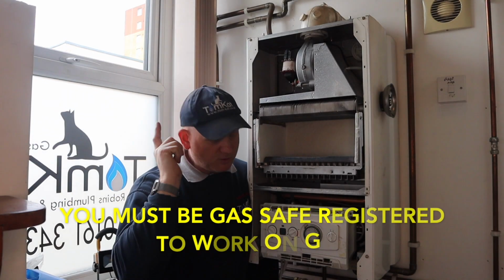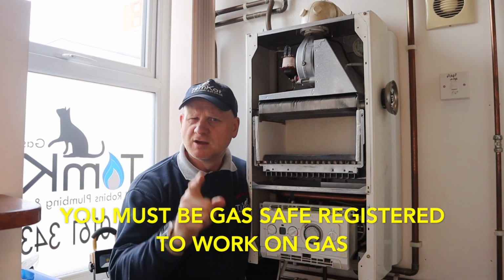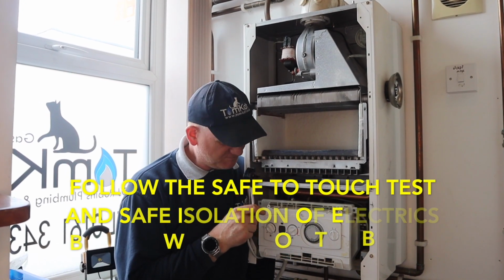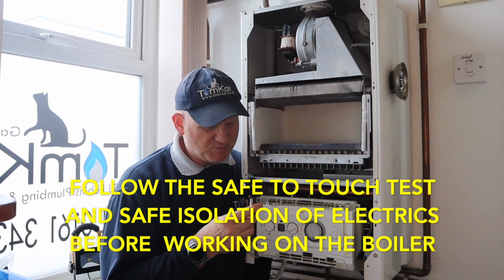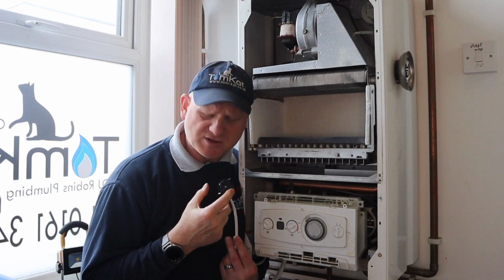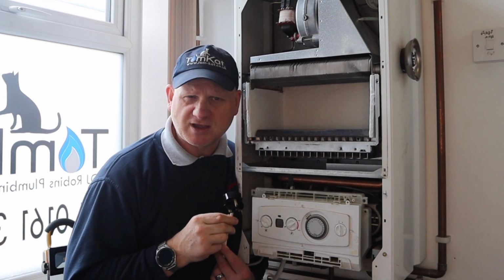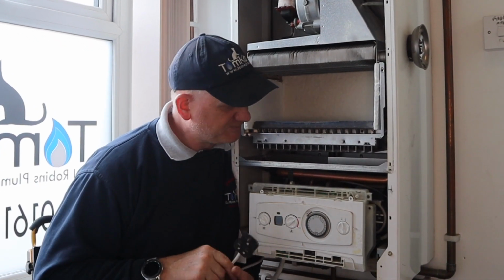So the first thing we're going to simulate broken is the starting point of this boiler, which is the pump. So, remember, we're following health and safety. I've removed the plug. And yes guys, if your boiler is fitted on a plug, you should have a 3 amp fuse in there, and it should be on an unswitched socket. Best practice would be a fuse spur, but this is on a plug.